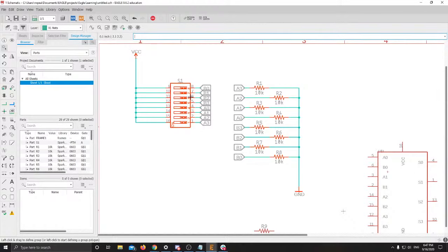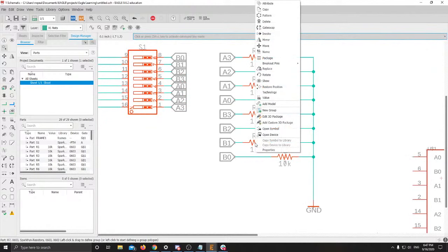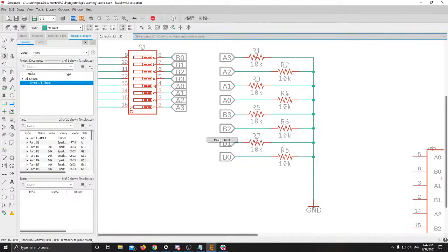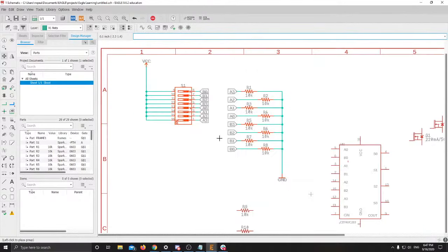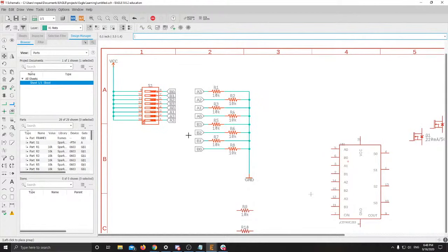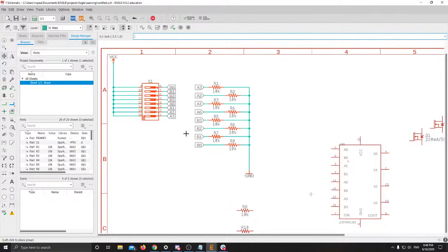And I'm going to right click on just one of the components at the origin. The resistor is usually the easiest. And then click move. Usually that just selects the one, so I'll hit escape. But then if I right click again, it'll give me the option to move the group. And then you can see it lets me move everything at once. This tool can be a little bit finicky, so if it doesn't work, that's not a big deal. But it is nice, especially when you want to move a big group of things around.